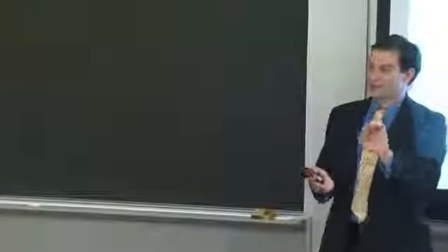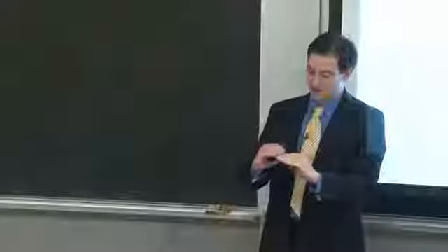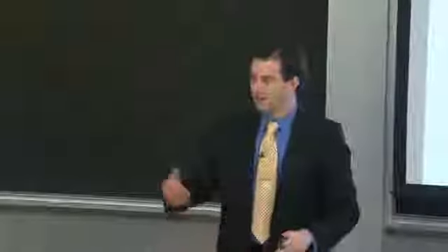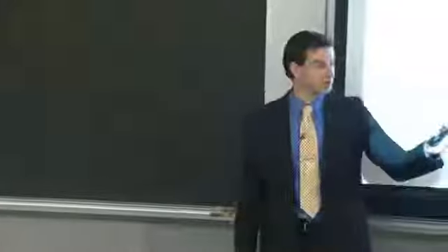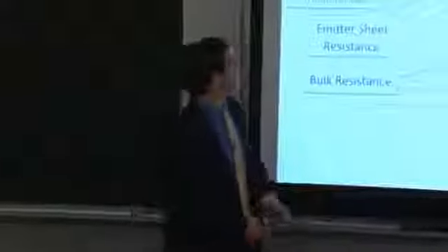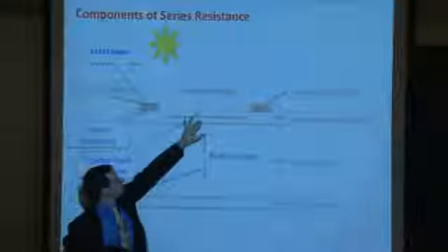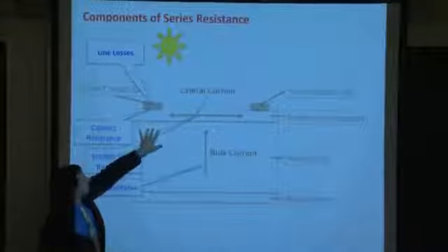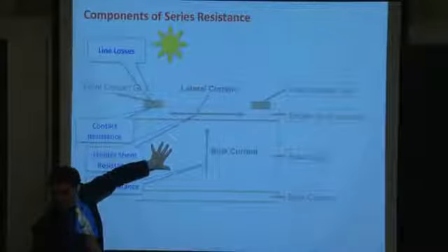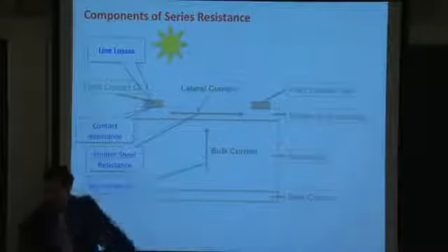So when you fire your contact metallization, when you create the contact between your metal and your semiconductor underneath, you run the risk of having atoms diffuse into your device and hurting the efficiency, hurting the ability of the solar cell to collect carriers. We'll hear more about that on Tuesday. So it becomes an impurity? Yeah, exactly. It becomes an impurity, in this case, unintentional. So just remember where the contact is right here in the emitter. If it diffuses into the emitter, it's okay. The electrons at this point are the majority carriers, but if the metal diffuses all the way into the bulk, the electrons inside of the bulk are minority carriers, and they can be impacted by the presence of that copper there.